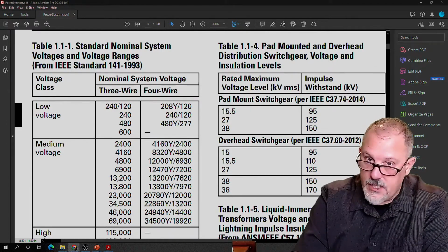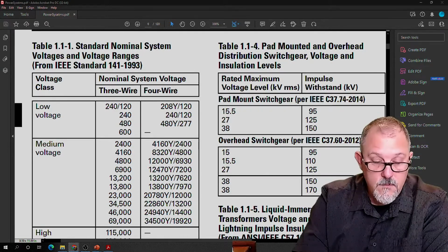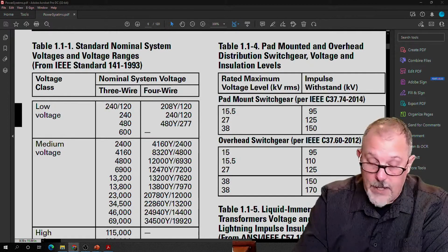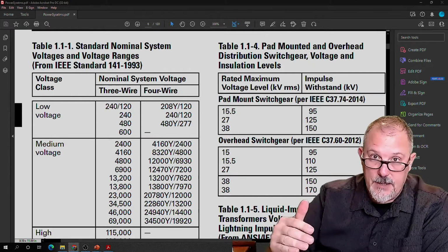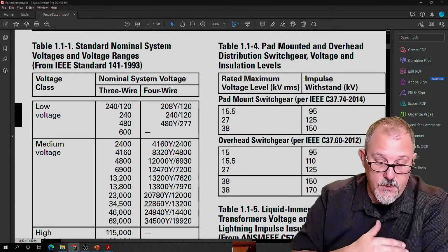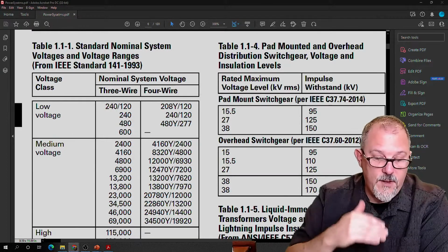There's no change in synchronous speed. The percent slip varies based on 1 over voltage squared, and you'll increase the slip by 23% for a 10% reduction in voltage. Full load speed will decrease by 1.5%.